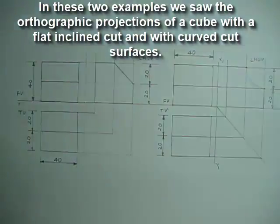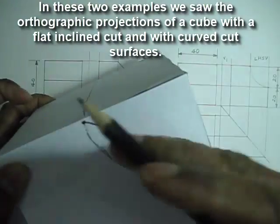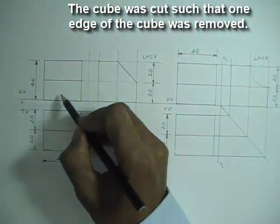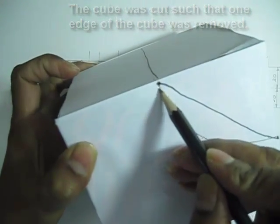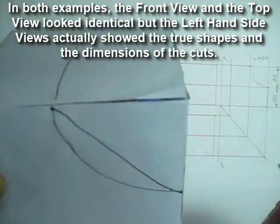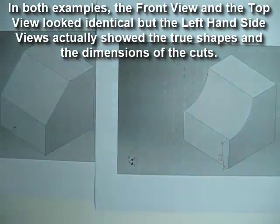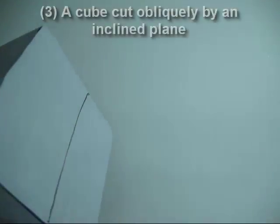So in these two examples we saw the orthographic projections of a cube with a flat inclined cut and with curved cut surfaces. The cube was cut such that one edge of the cube was removed, and the cutting planes always cut the edges midway. So the front view and the top view looked identical, but the left hand side views actually showed the true shapes and dimensions. So we have completed these two examples.